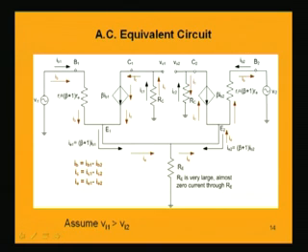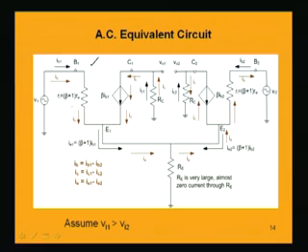The collector C1 through this resistance Rc is grounded. So, if we consider only this Q1 circuit or transistor Q1 model, then the B1, C1, E1 points give you the model of the transistor Q1, which is having the input resistance Ri, which is beta plus 1 into Re, and the current Ic1, that is beta times of Ib1.